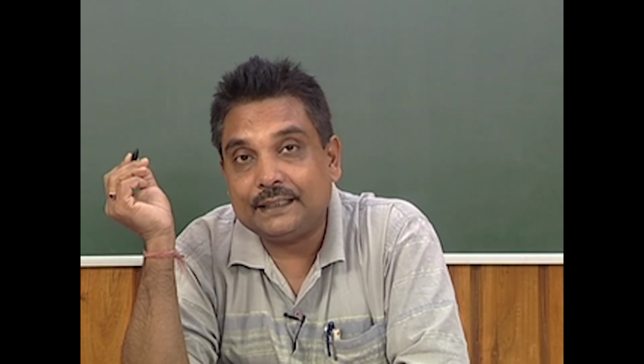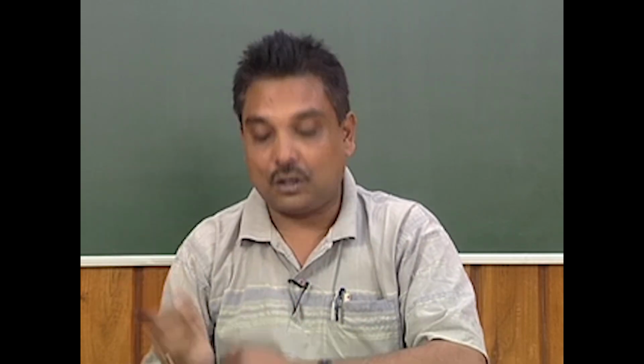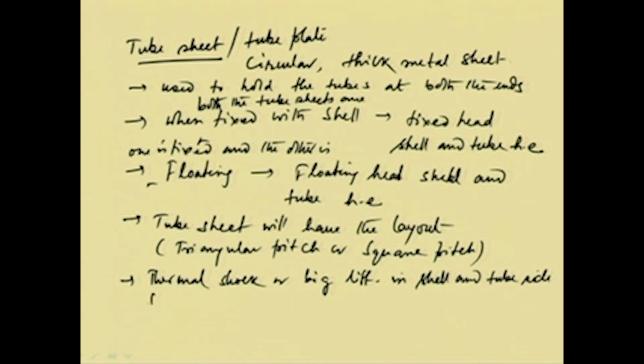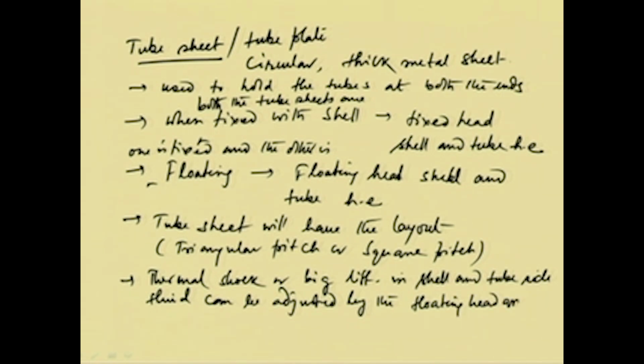The reason behind this is that when there is a thermal shock, that means a big difference in shell and tube side fluid temperature, it can be adjusted by the floating head arrangement.